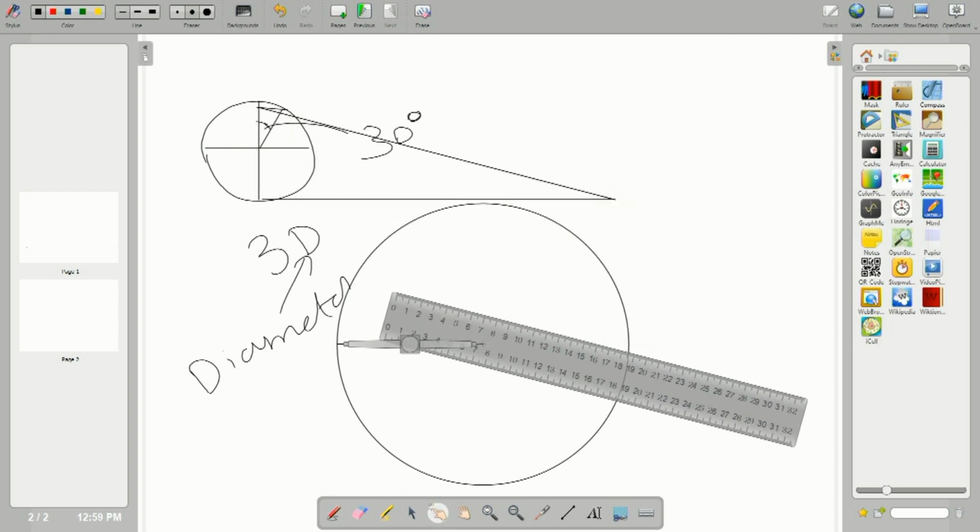this line gives pi d, the circumference of a circle. I have simply shown it here because of insufficient tools. Actually, if you want to find the circumference of a circle, draw a circle and two lines, vertical and horizontal, from the center. From the bottom of the vertical line draw a straight line with a measurement of 3 times the diameter.